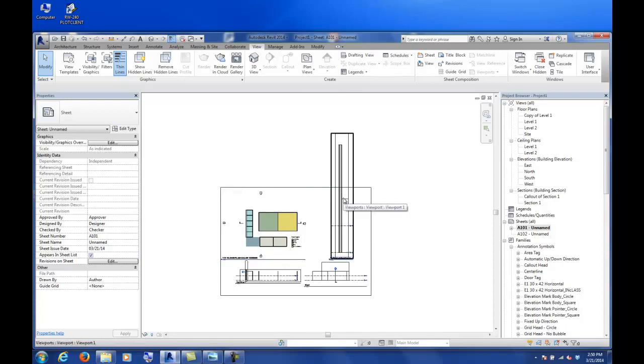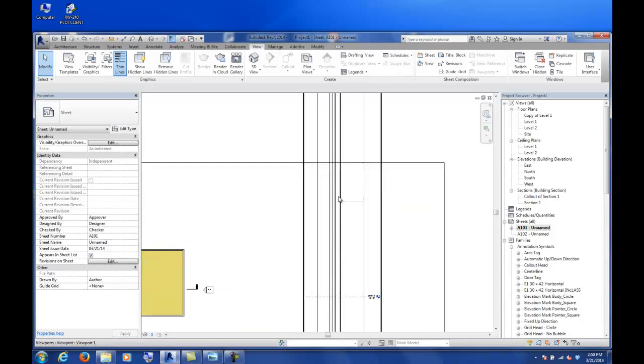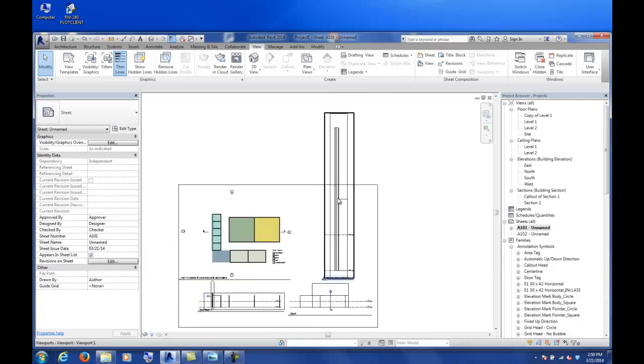Oops. Revit has this really nice option, which a lot of times people will do in CAD. When you've got a really tall wall section and a lot of it's the same in between, you would chop up that wall section a little bit and kind of bring it together. But the trouble of doing that, and you have the little break lines, especially in CAD, is that once you do that, if you ever had to measure what the height was of that wall section, you kind of just lost that measurement.